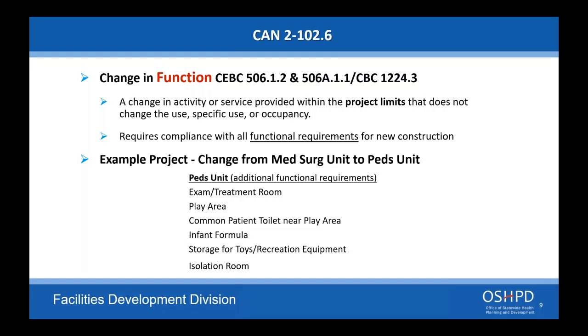Perfect. Next question for you is, if imaging equipment change out only, would the habitable room requirements at CBC 407.4.1 apply? Yes, this is primarily a problem when they're not in suites. We are trying to deal with that issue right now because you don't want an MRI with a door going out to a corridor. That basically goes in the face of any logic for those types of rooms. So we are trying to deal with that, but they are considered habitable rooms.